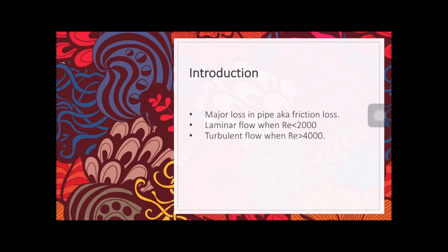As we know, liquids or gas that passes through pipes or ducts is occasionally used in heating and cooling applications. These are the types of fluid that are used. When the fluid is forced to flow through a system, it will experience some losses due to the frictional force that occurs inside the pipe. The continual loss of energy or total head of the fluid is the result of the frictional resistance to which it is subjected while flowing inside the straight pipe.